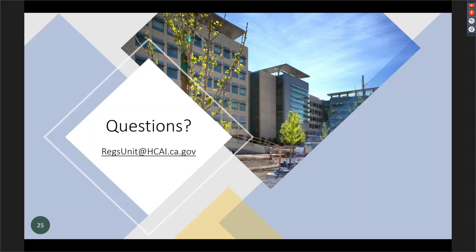One of the questions we get is, we can't make revisions to an approved set of drawings, but you do it all the time when you annotate an RFI or an ASI on a set of plans. You cloud it, you delta it, and you put a number on there. We'd expect the same thing with an NMA. Again, we're not approving the drawings, we're just concurring with the changes, not a material change. So you would just cloud it, delta it, and put an NMA number.